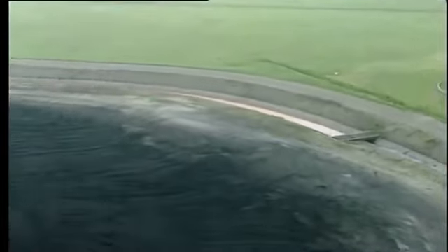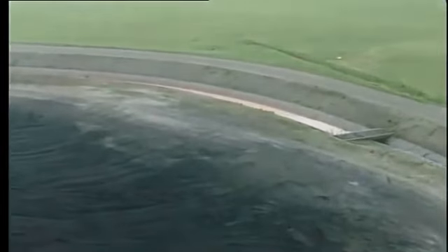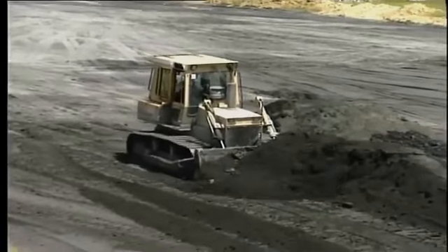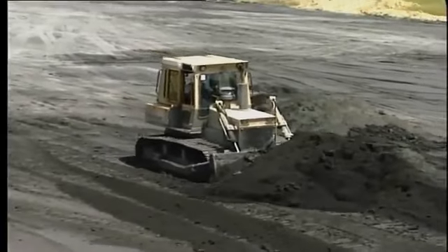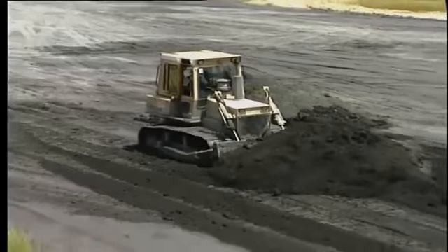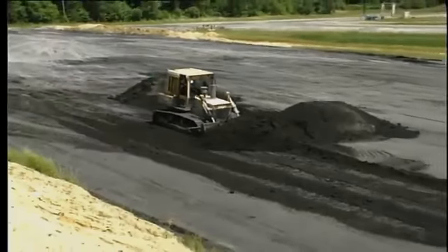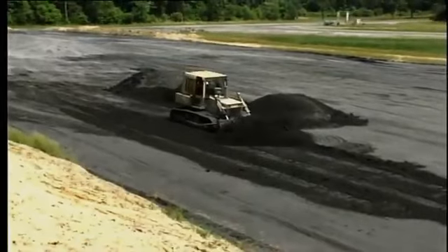Stormwater runoff must be collected and treated to remove solids. A liner is also required for the landfill area where solid waste is eventually laid to rest. In fact, there are definite rules and regulations which govern the construction and operation of a certified landfill site.